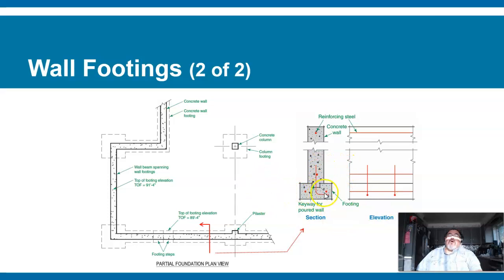And what we saw in this picture is little dots: 2 bars here, 1 bar up here, 1 bar up here, traveling horizontal the length. So that's what you have. And when I spoke about a masonry unit, you take this shape and figure out what its value is in material at 1 lineal foot, just traveling 1 foot.